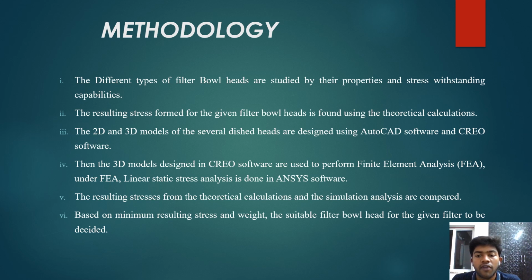are used to perform the finite element analysis, FEA, under the linear static stress analysis in the ANSYS software. Now, the resulting stress from the theoretical calculation and the simulation results from the ANSYS software are compared. Based on the minimum resulting stress and the weight, the suitable filter head for a given filter is decided.